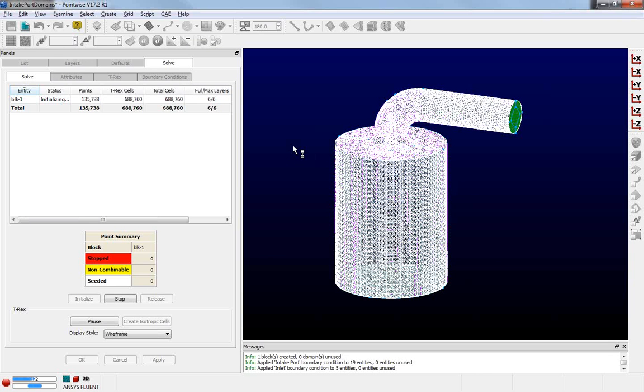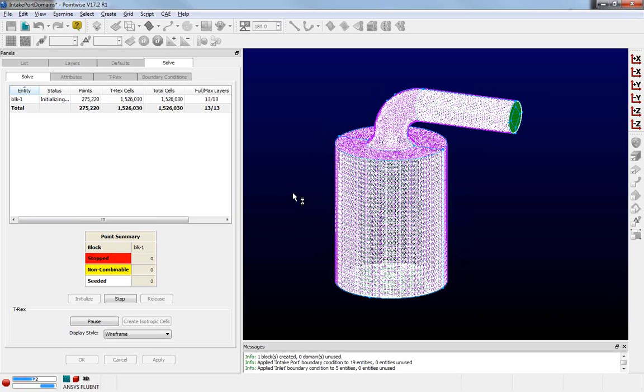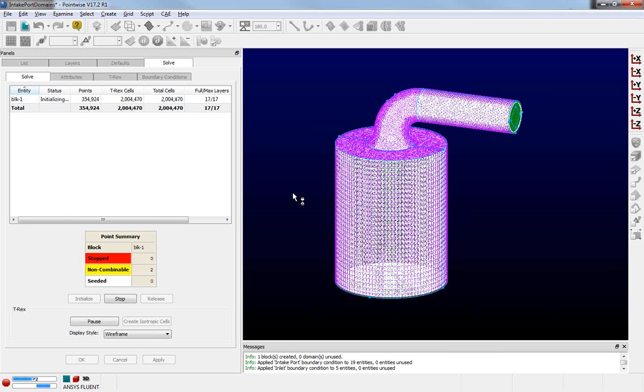This is your boundary layer mesh that's growing. As it grows inwards, you'll have cells start to stop because of isotropy or collisions. Those cells you'll see show up in red in this front. Eventually, the entire front will be red because they have all stopped, and this is to be expected. Once that happens, that front will be passed off to our isotropic tet mesher, which will fill the remainder of the volume with isotropic tets. At that point, initialization will be finished.